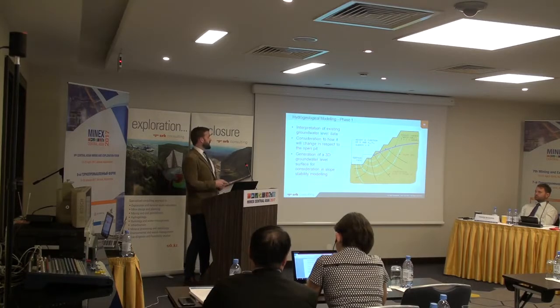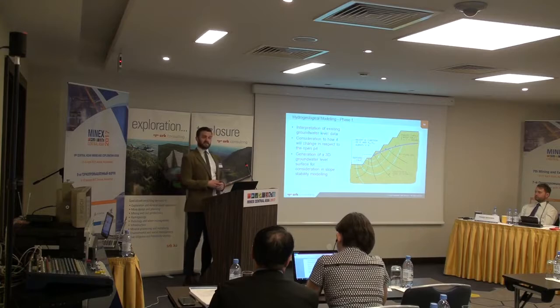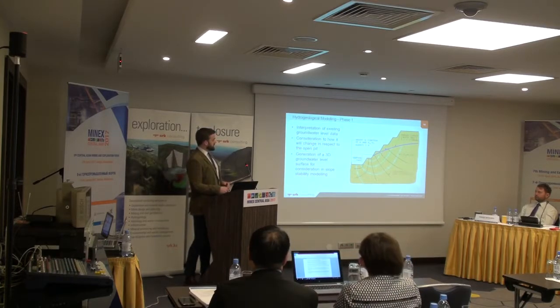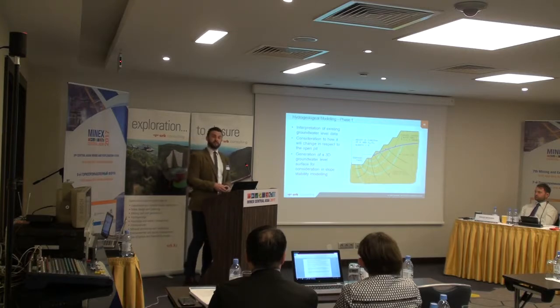And usually we generate a 3D groundwater level surface for consideration in the pit slope design. And here we can see we have an existing groundwater level which usually has some drawdown to the toe of the slope. This is the initial phase of the hydrogeological modelling or understanding of the deposit.